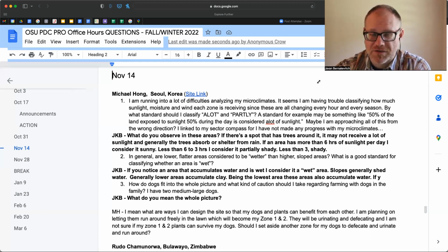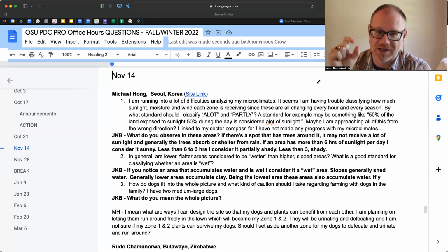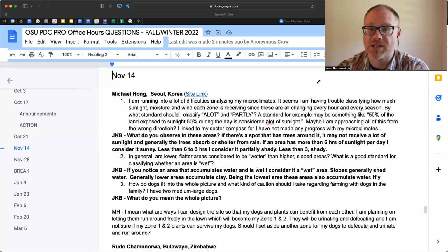And this has to do with the fact that raindrops are violent affairs if you are a soil ped. And a soil ped, again, is a soil molecule that is sand, silt, and clay. So if we have the percussive effects of a raindrop that comes down and hits a soil ped, it breaks apart the sand, silt, and clay and then puts it into solution. And when we have overland run, all of that solution comes with it.